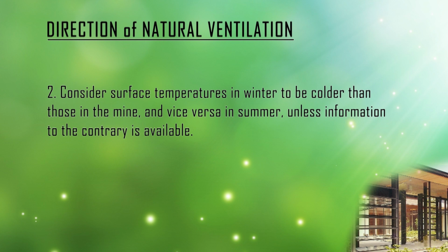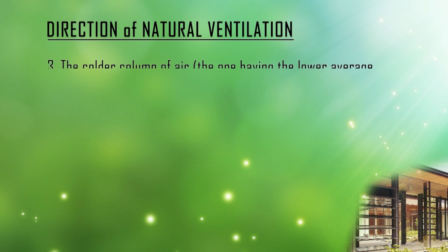This means during winter the outer atmosphere is colder as compared to mines, then the air has a tendency to flow from mines to surface. Thus, this is the reverse in case of summer. In summer, the surface temperature is high as compared to mine temperature, and there will be the flow of air from surface to underground. So, there may be a reversal of natural ventilation during the weather, that is, if in winter it is from mines to surface, then in summer it is from surface to underground mines.